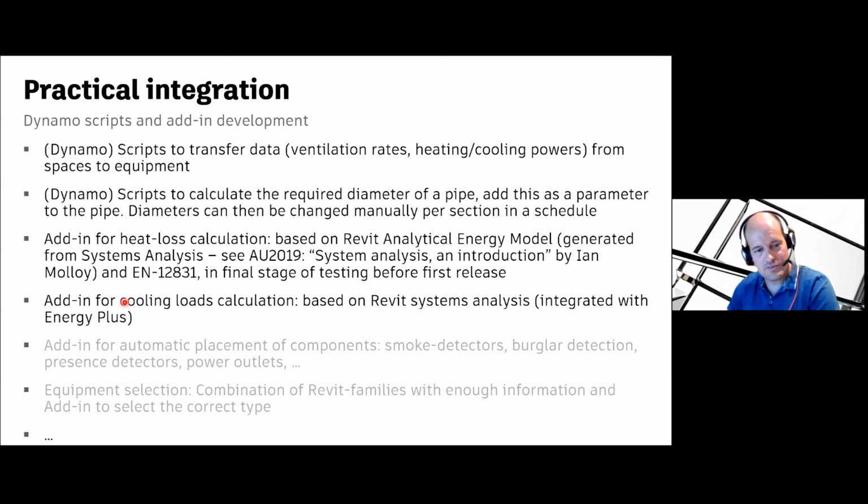We have a similar add-in where we calculate the cooling loads, which is based on the same analytical energy model, but also the integration with EnergyPlus. So we use the EnergyPlus integration with Revit to calculate the cooling loads. Those two at the bottom are ones that are on the list to be developed. Automatic placement of components, which follow a certain structure.